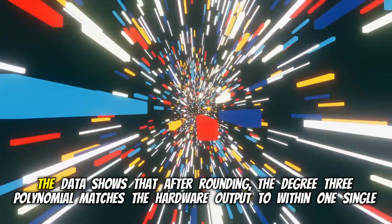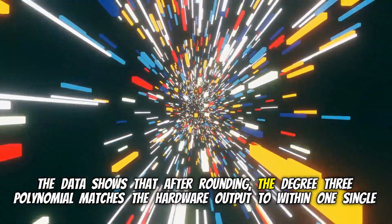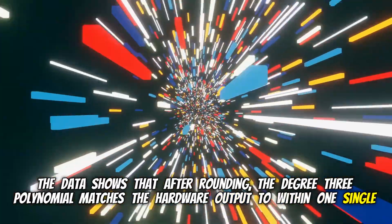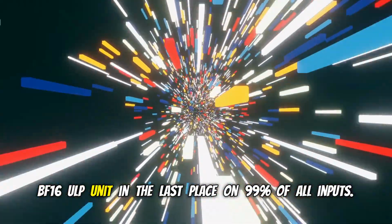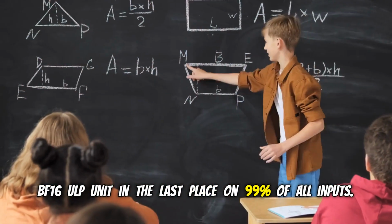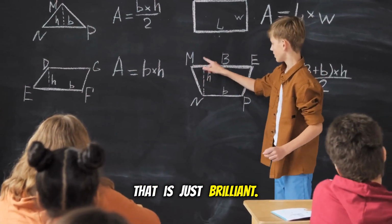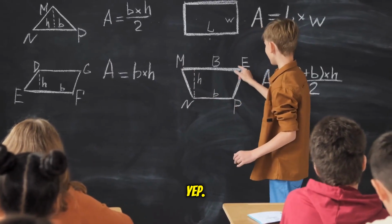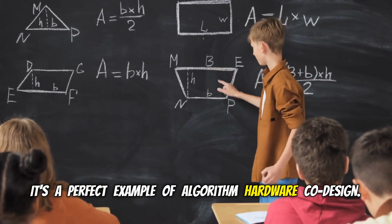It doesn't. The data shows that after rounding, the degree 3 polynomial matches the hardware output to within one single BF16 ULP, unit in the last place, on 99% of all inputs. That is just brilliant. The final data format is basically a low-pass filter for the approximation noise. Yep. It's a perfect example of algorithm hardware co-design.